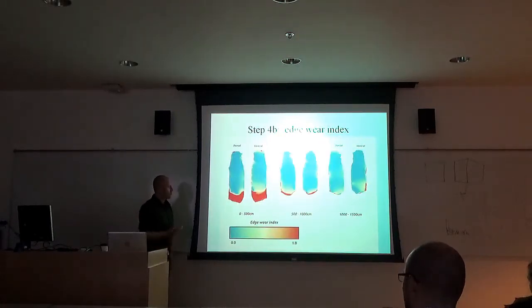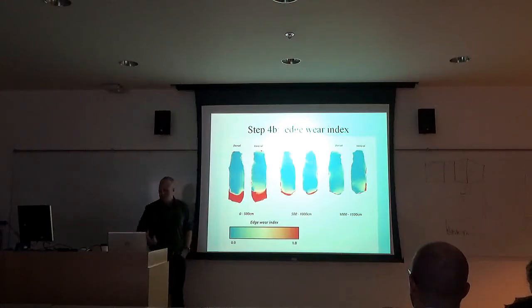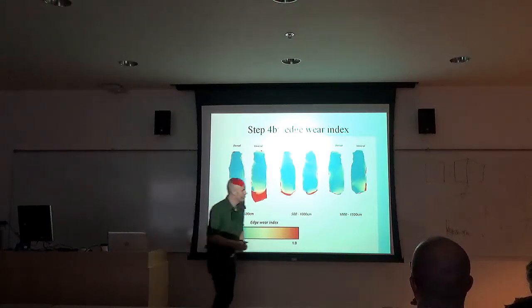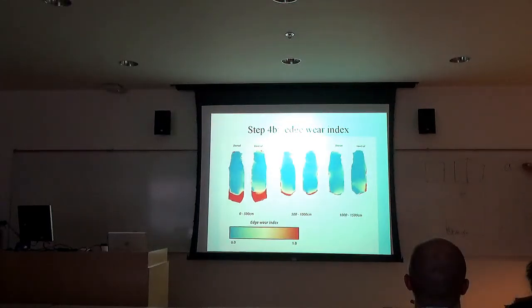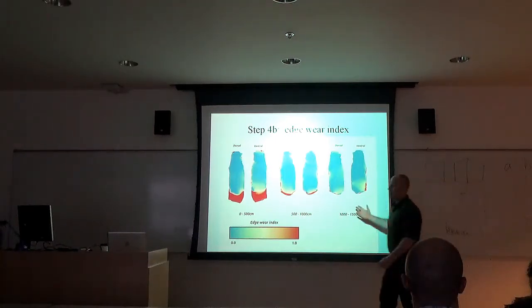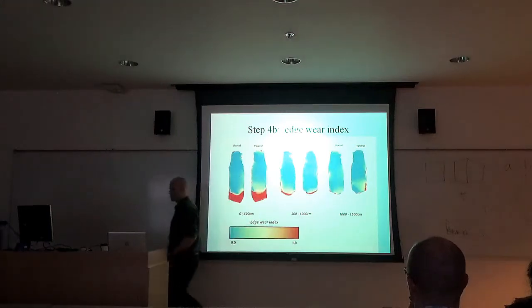So the other thing I really like about this is, of course, if you go surface A unworn minus B, which is worn, equals C, and then you go, I believe, A over C, that creates a wear intensity index.